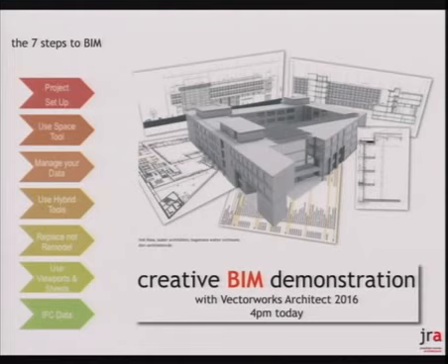I will definitely use some of the hybrid tools: walls, windows, doors, slabs, perhaps a roof. And I'll talk about the overall concept of replacing data. So instead of redrawing everything, like we would with traditional drafting and lines or drawing with polygons and rectangles, where every time the wall thickness changes you've got to redraw that wall, we should be able to replace a wall with a different style of wall. Replacing data is a real cornerstone of the BIM process.